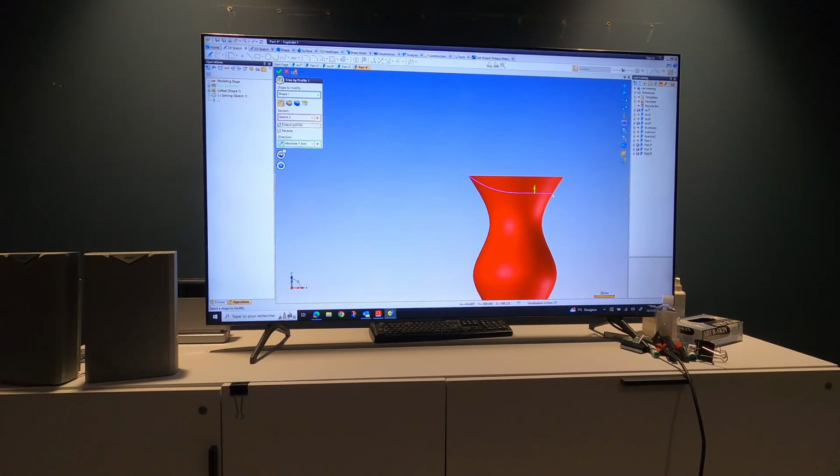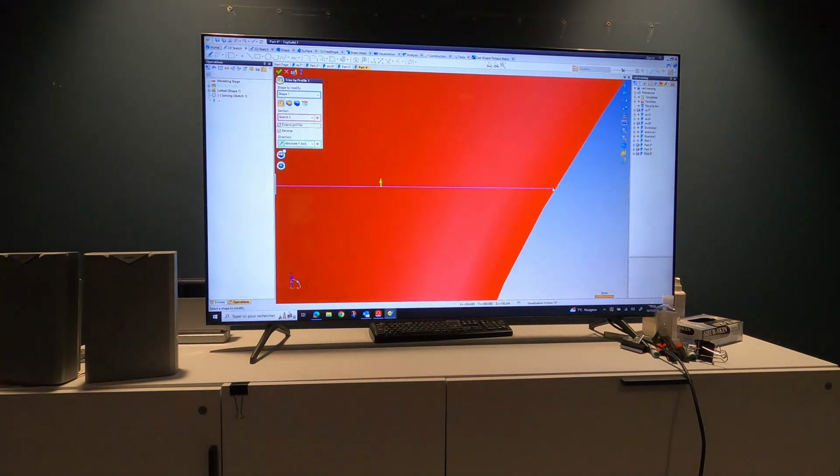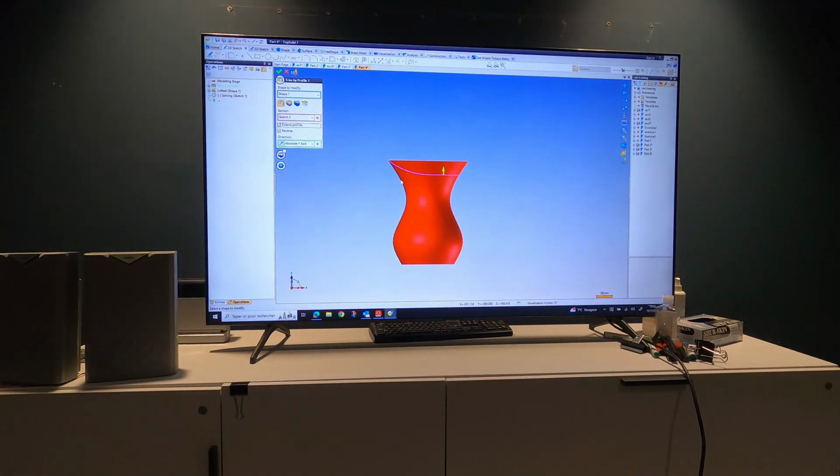It's like the wire to cut the butter. You take it on both sides and you go through the butter. If one of your fingers is in the butter, it doesn't work. It is the same, so you have to extend the wire to make sure it goes out. And here you have an option to say extend profile, then it makes it automatically. So if we're ever stuck in that phase, make sure all the time when you do a profile like this to trim, that it goes out.